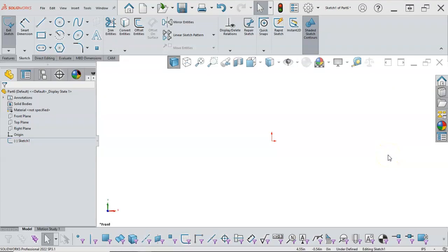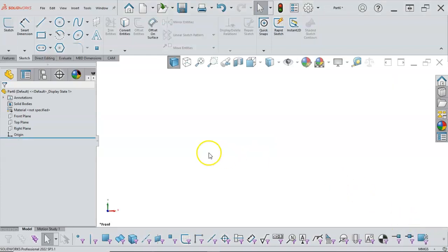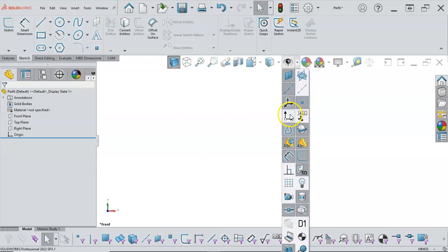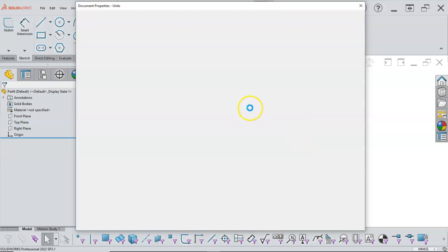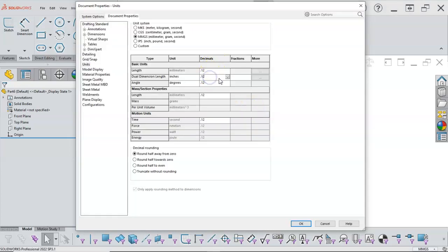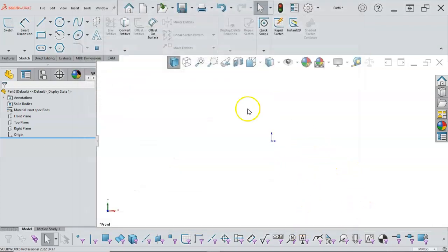So I'm going to do this in a slightly different order than the snippets. If you are in a sketch, and right now the sketch is empty, so if I decide that I want to go to millimeters, grams, and seconds, it's going to kick me out of the sketch, and because the sketch was empty, it just closes. Since I brought up the origin, we'll go to the down arrow and turn on the origin. And again with the units, if I want to verify my metric units, 2 place decimals, and then we could set the inch to 3 place decimals, we can go back and forth.